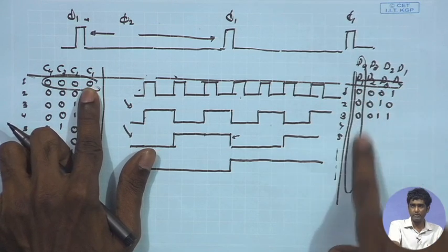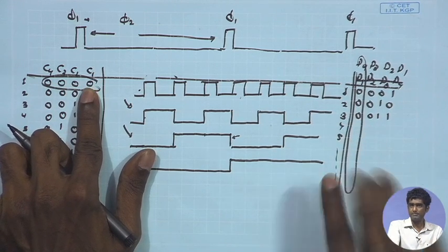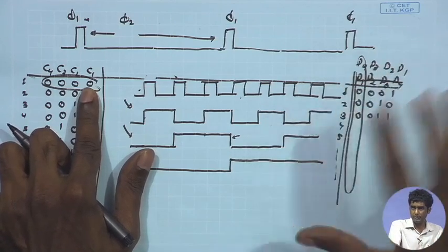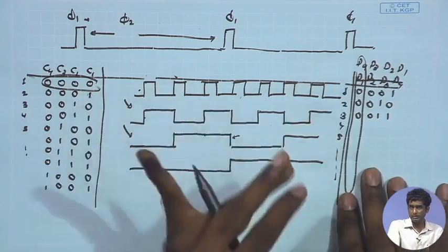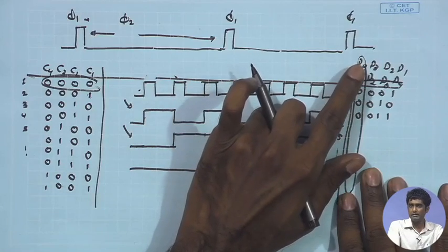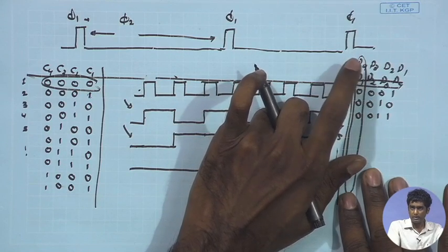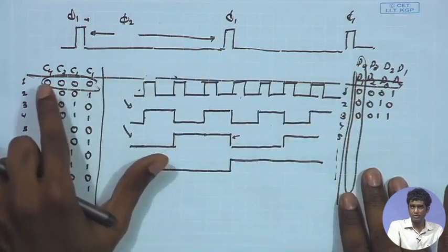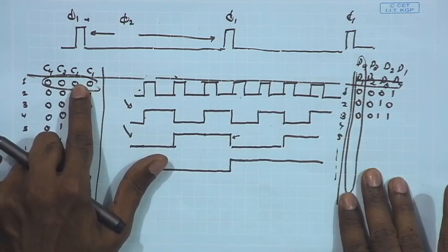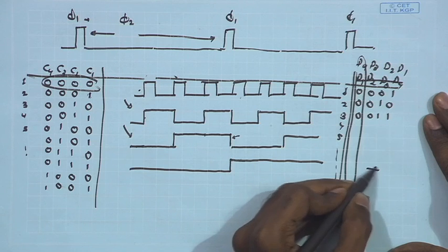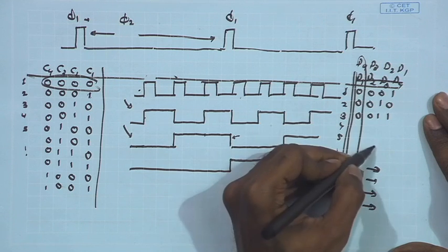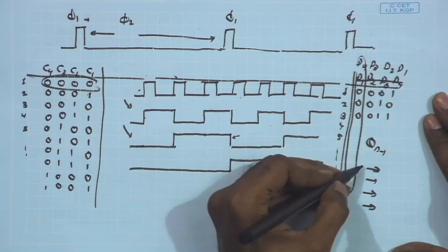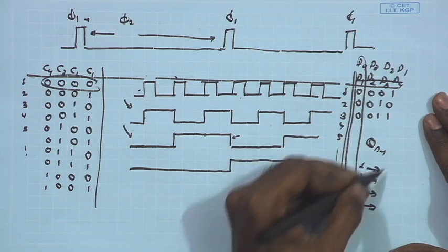Likewise, D3 is going to have a truth table, and each of these can be implemented using a K map. You can conveniently reduce it, with 4 inputs, and arrive at the logic which is going to give me the value of D4, or a logic function for D4, as a function of the previous outputs. So, if I have the previous outputs, I can call it Q n minus 1, meaning previous step output Q n minus 1, 1, 2, 3, 4 available in the previous state.